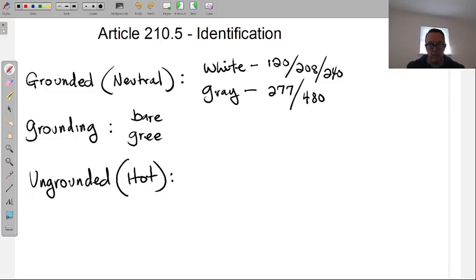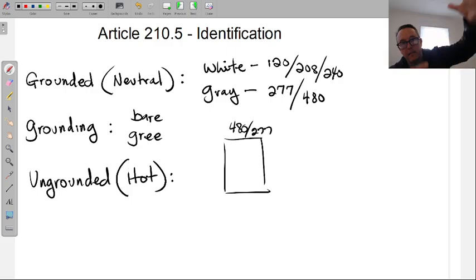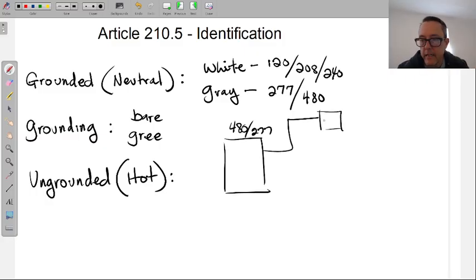So in the building somewhere, even in multiple places, you'll have transformers that are stepping down a panel that's 480, 277, because that's what you got into the building, because you want the high voltage. This is feeding your HVAC circuits or your air conditioners, your motors, whatever pumps you have in the building, all of that machinery stuff.